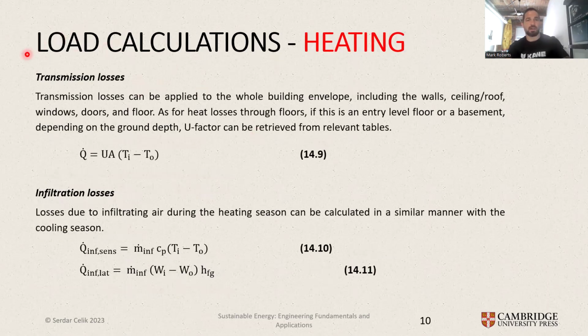So when we're heating, we can have heat losses, and again, these are going to be fairly similar. The amount of the heat loss is just going to be based on the heat transfer coefficient, the area of the building, and whatever the temperature difference is through which the heat is flowing. So if we're keeping our house around 70 in an environment where the temperature outside is 40, and we're talking in terms of Fahrenheit, we can get an idea about the heat. Obviously, the lower the temperature difference, the less heat loss, or heating required, for that building.